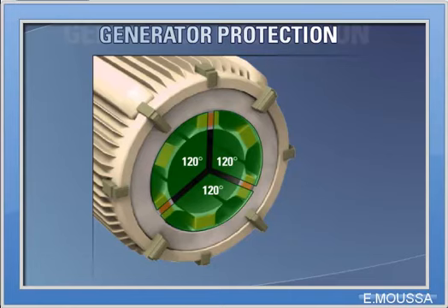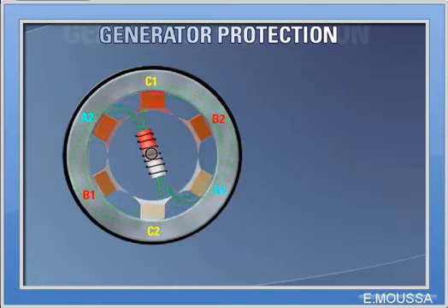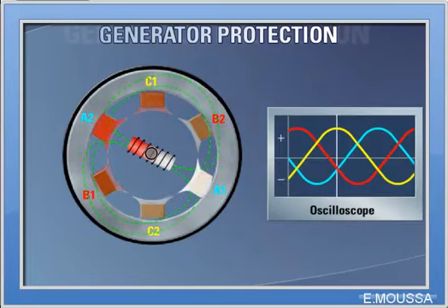It is called a two-pole generator because the stator has two electromagnetic poles per phase. One side of each pair of windings is connected together, while the other side is connected to our three-phase load. If we plot a graph of the voltage which appears across each of our load resistors against time as the exciter rotates through one revolution, we will see the waveforms shown.